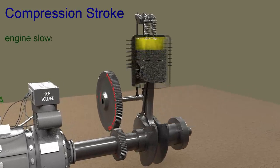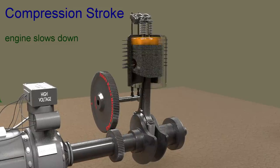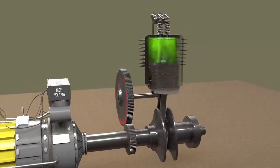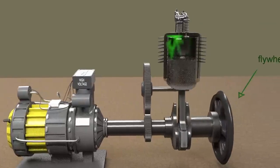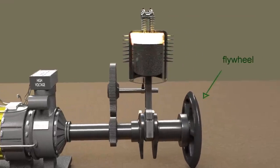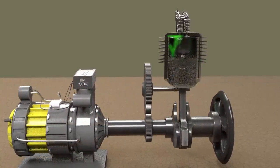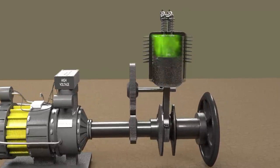This energy comes from the kinetic energy stored in moving parts attached to engine by slowing them down, and there is fluctuation of speed. A flywheel is connected to limit this fluctuation of speed. A flywheel is wheel with high moment of inertia, which means more energy is required to increase or decrease its rotational speed, or in other words, to accelerate or decelerate it.